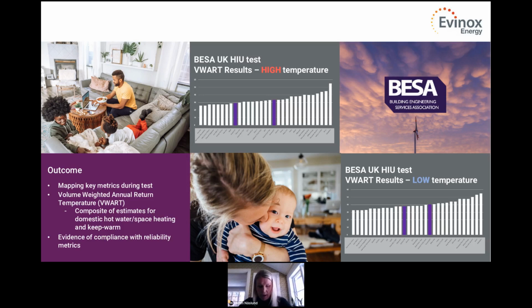The test results will show how these HIUs will perform under perfect laboratory conditions. One example here, which is what I mentioned earlier: if the radiator system has not been commissioned and the radiators are returning a higher return temperature, the HIUs will not be able to perform as per this test. And that is because the secondary return temperature in the test is fixed.